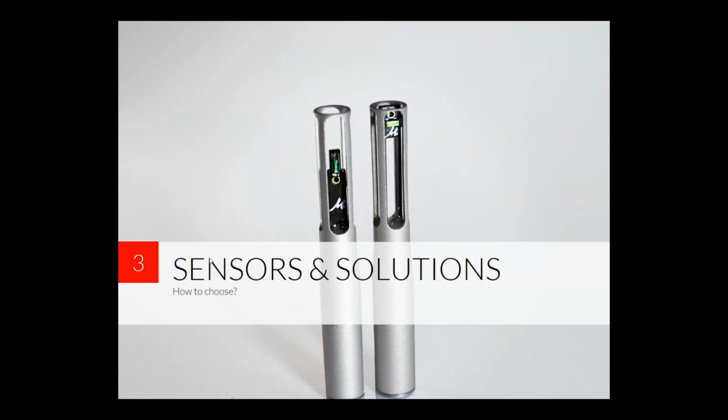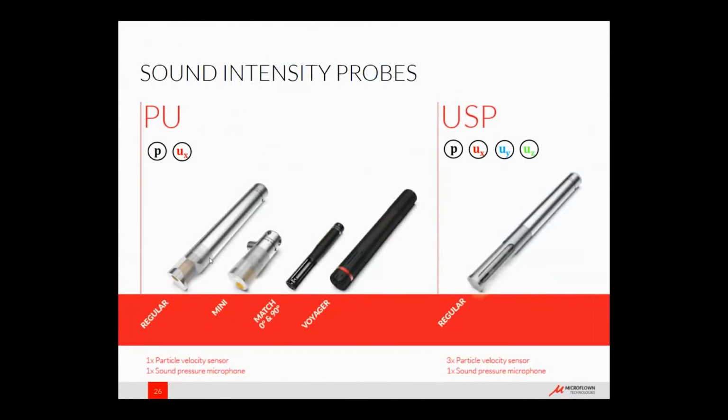So, looking quickly at some sensors and solutions. The most commonly used sensors are seen here, which we also see later on in our solutions. We have 1D and 3D probes. In the so-called PU probes, we combine one traditional sound pressure microphone with a microphone particle velocity sensor.